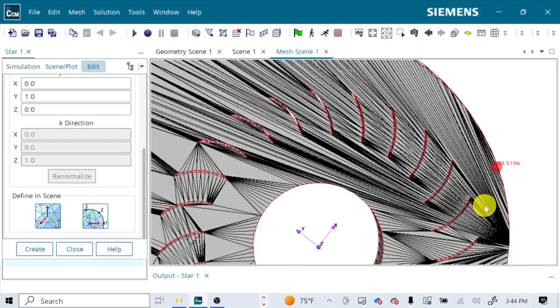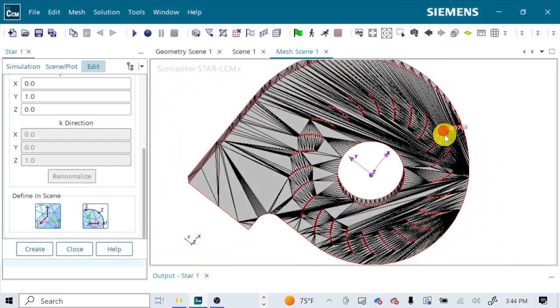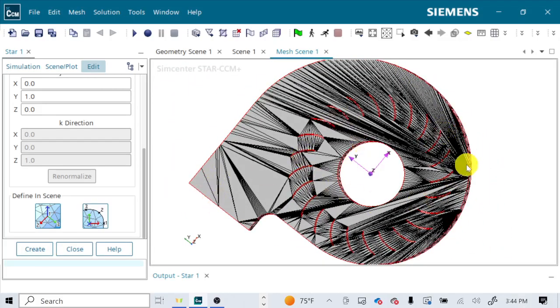But again, if you don't know what the center of rotation is, you can use the 3 points on a circle method to find it. If you do know what it is, you can type in exact numbers and make the axis of rotation exactly what you want it to be. If you don't know it, you can find it to a very high degree of precision with the 3 points on a circle bit.